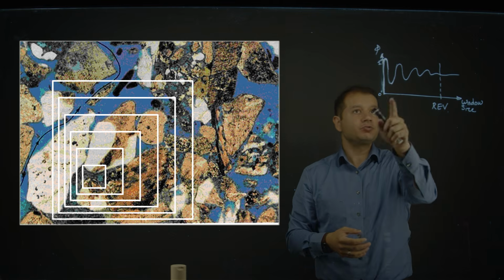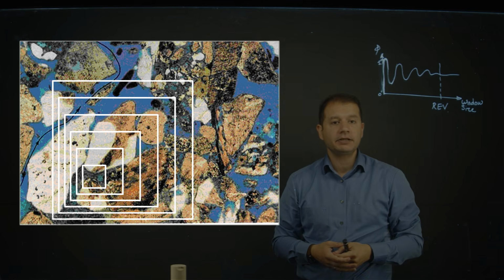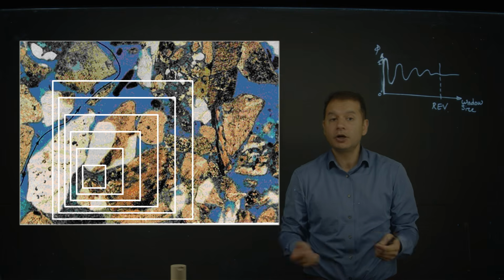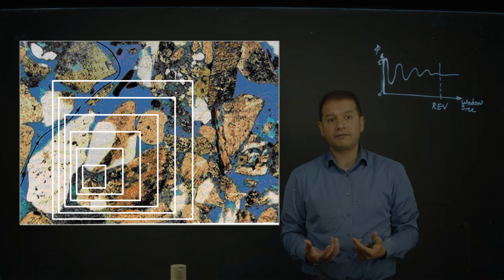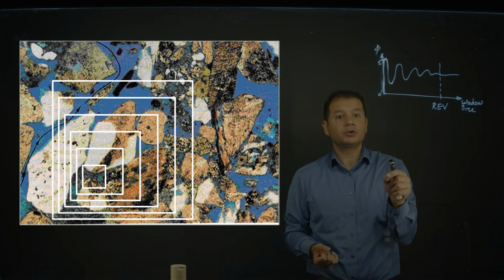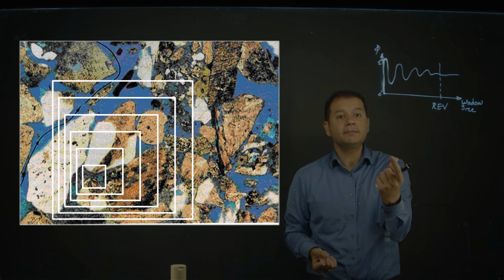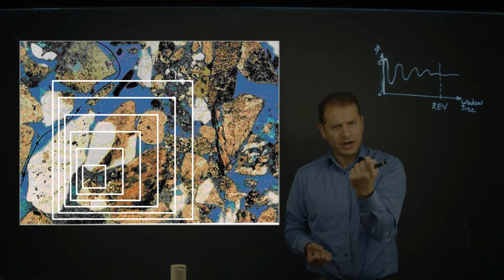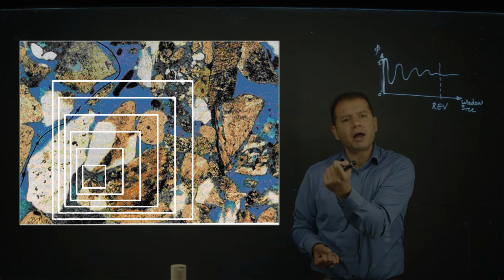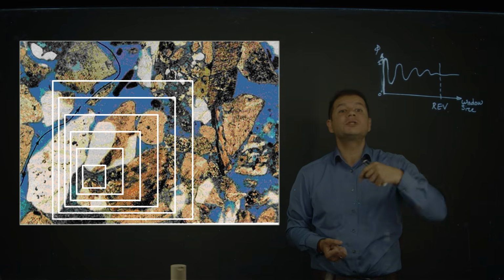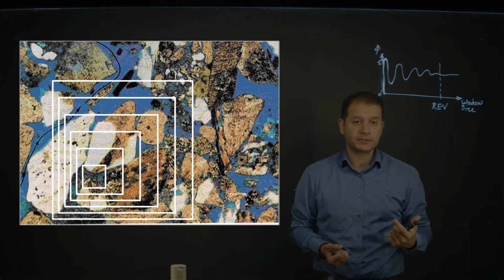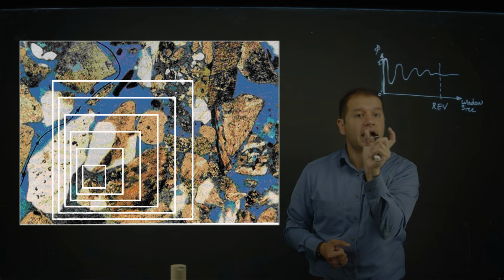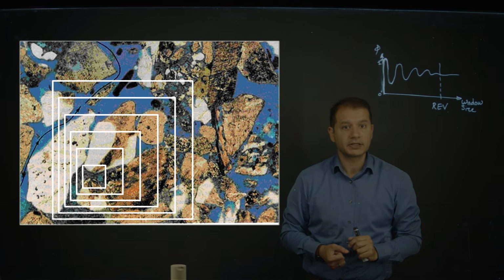That is valid here for porosity, for example, in this experiment, but for fluid physics like density, viscosity, etc., the very same approach is valid because we want to report density also in a continuum representative way. So REV is small enough to be a point-wise measure of the property, but also big enough to dampen the variations and fluctuations. So this is the scale at which I would like to represent my porosity.